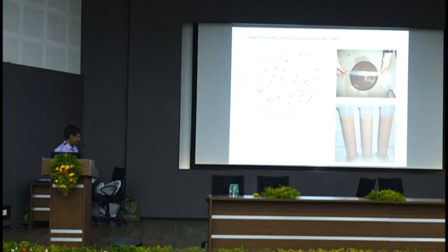So these are some of the very rudimentary tests we do. One we call flow, the other is bleeding. In self-compacting concrete, because many of you are from that concrete background, how do you measure whether it is flowable or not? Through the flow diameter, and other equipment is also there, for segregation and so on, the V test.